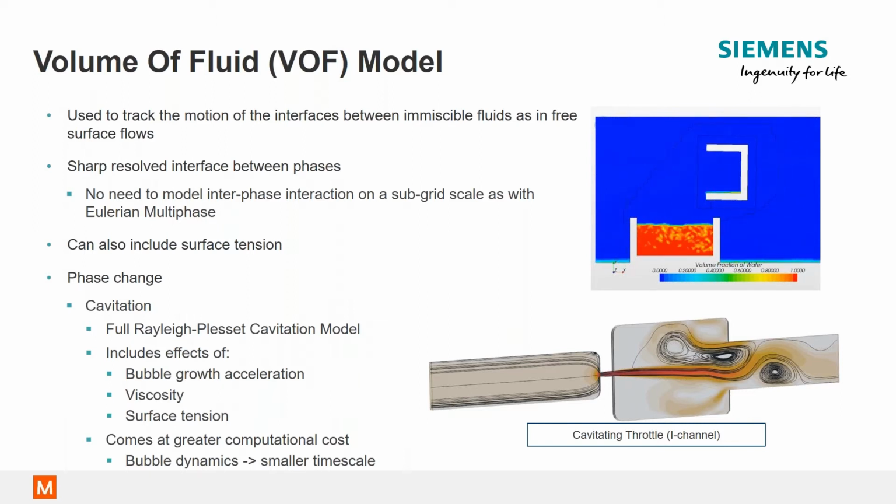When we use volume of fluid, we need to make sure that the time step is such that the CFL number normal to the free surface is less than 1. Otherwise, the interface will be diffuse and the distribution of the phases will eventually be wrong.